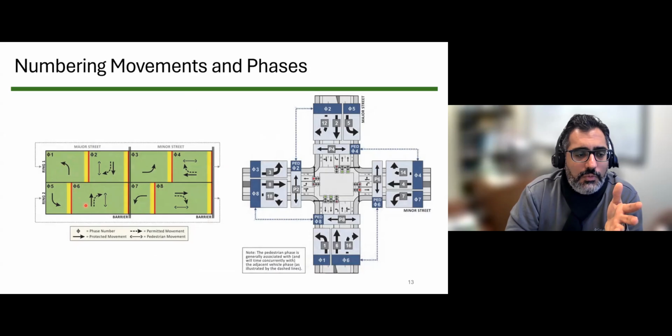So at some point, we went to through on the north and right turn on the northbound, but the left turn was still happening, mainly because of the demand. So we may have overlapping scenarios if we have actuated signals specifically. If we have pre-timed signals, most of the times we are just going to end up with non-overlapping phases.